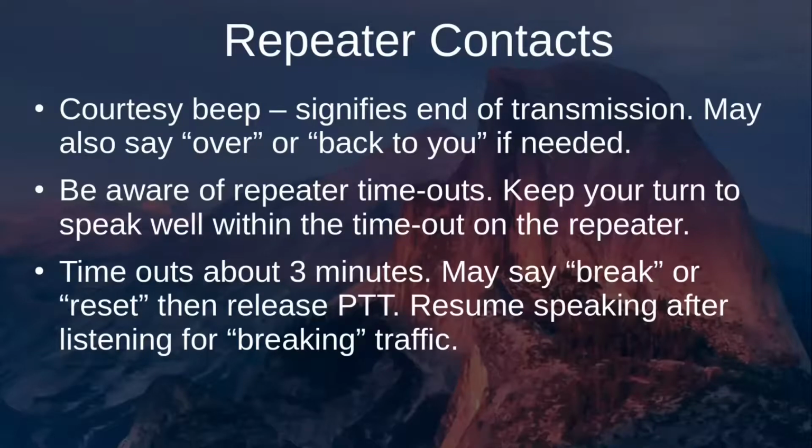Repeaters also have what's called timeouts. They don't allow continuous conversation without a limited period of time. Typically a repeater will time out at, let's say, approximately 3 minutes. That's probably one of the most common time frames. So it does not allow someone to speak for more than 3 minutes uninterrupted. If that person continues to speak beyond that 3-minute time frame, the repeater will reset itself and not allow any input or transmission, and prohibit the conversation for a period of time until it resets itself.